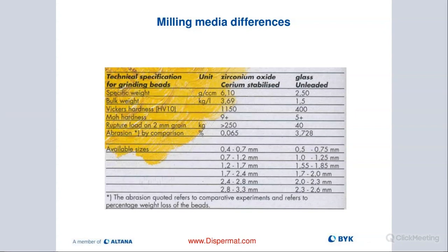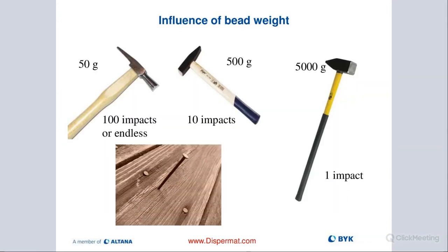And then we can really efficiently mill down from about 10 microns to about 1 to 2 microns very quickly on most formulas, and then even down to 600-700 nanometers with the same bead size. And if we want to go smaller with our primary particles, then we really need to start reducing the media size, and we go down progressively as we see our particle size getting reduced also. That's important to remember, is that we need to also go down with our media size as we're getting smaller.